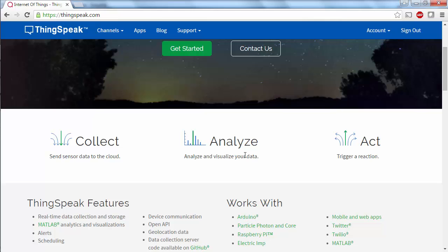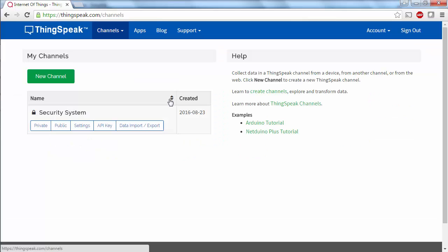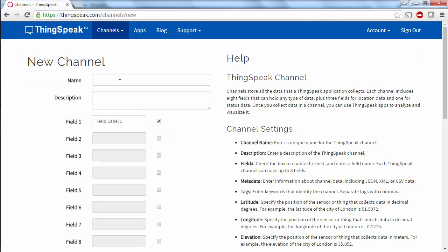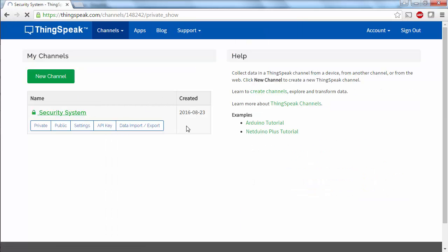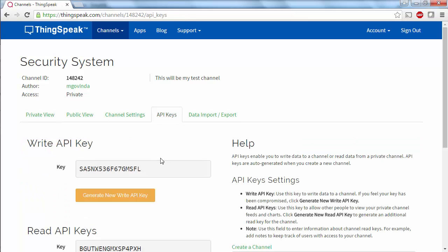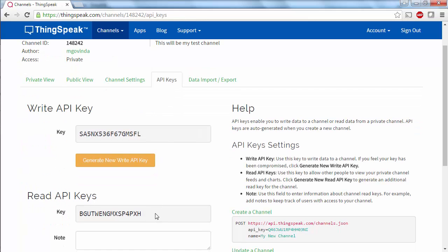We will now see how the ACT portion of ThingSpeak helped me in the context of this demo. You can create a new channel and fill out all the necessary details about the channel: title, description, and field. Instead of creating a new channel now, let's go take a look at the one that I've already created. To get the right API key that I showed in the Simulink model, you will have to go to this section under your channel.